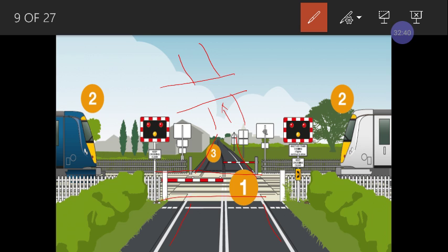But when we are going to allow the vehicular passing, here in the center there is a gap, because the two rails are higher by 20 centimeters, so there will be a gap. This gap will be filled like this, so that there is easy movement of the vehicles.